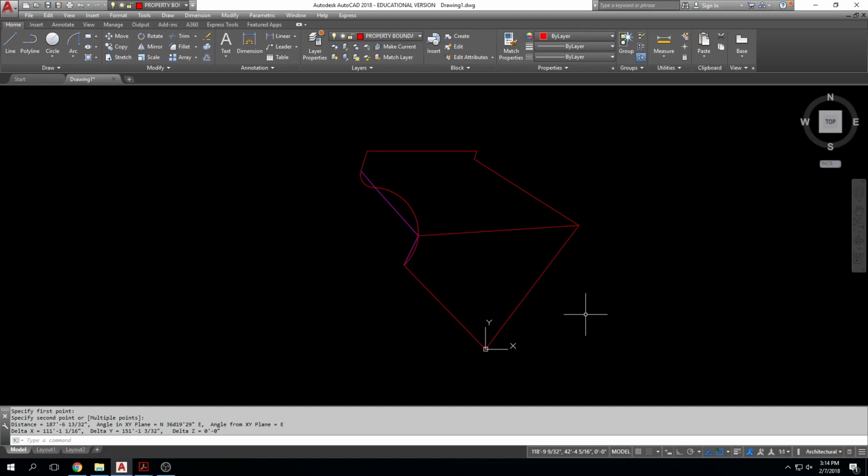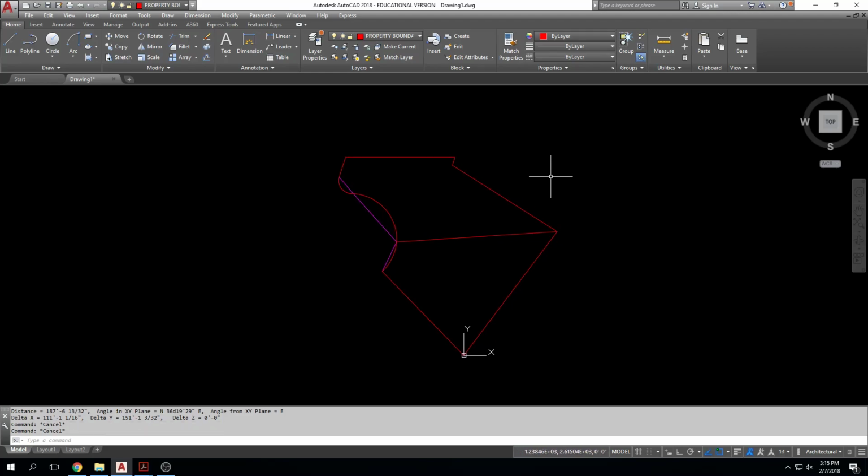It's tricky, and I like to show you every possibility that can happen so you're not freaked out and can't get it right because you don't know what to do. If it's architectural and you measure it and it's the same as on the site plan, then you know you've done it right. If it's architectural and you measure it and it's really, really small, by a factor of 12, then you need to scale it up by a factor of 12 and it will be correct. So we've scaled it up and it's time for us to print.